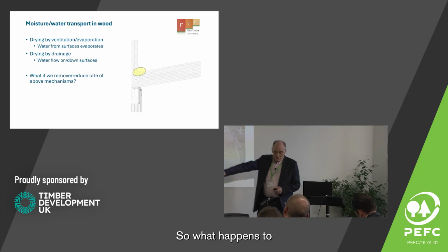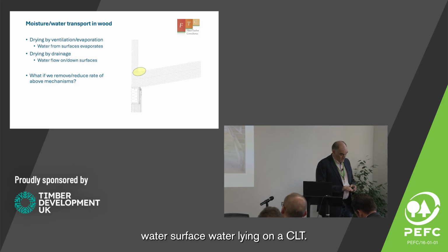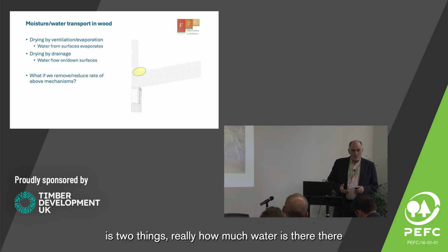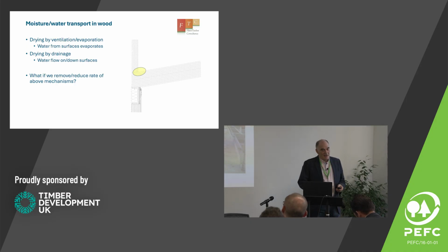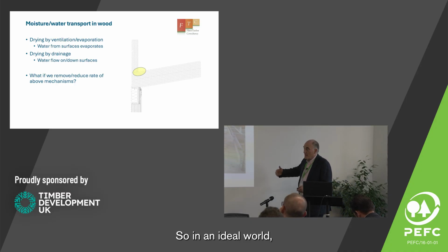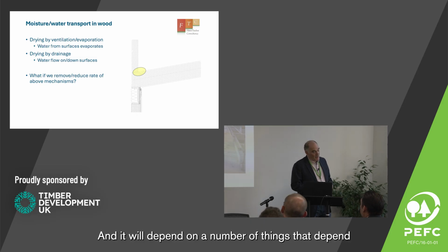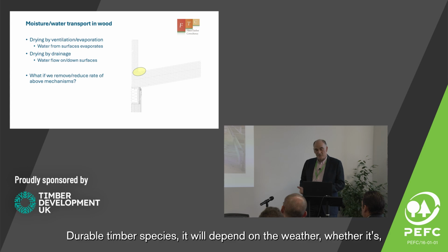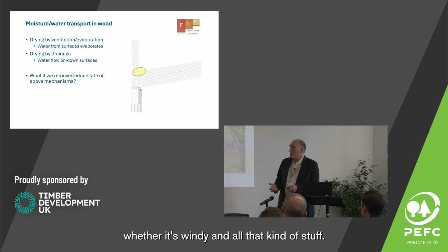So what happens to water? A typical example is some surface water lying on a CLT. What we're concerned about is two things really: how much water is there, how long it's going to stay there, and where it's going to go. In an ideal world, it would just evaporate. It will depend on a number of things: the timber species, how durable the species is, and the weather, whether it's raining more, whether it's windy and all that kind of stuff.